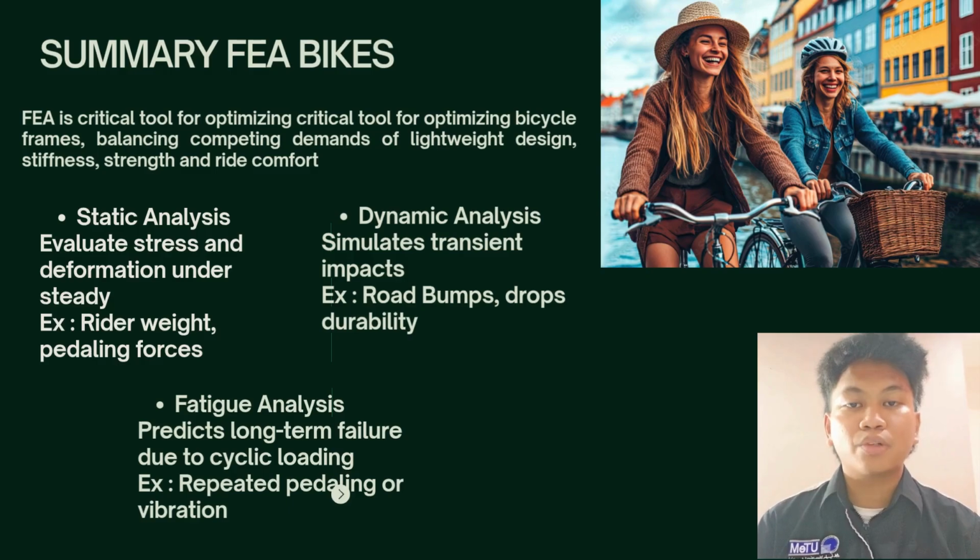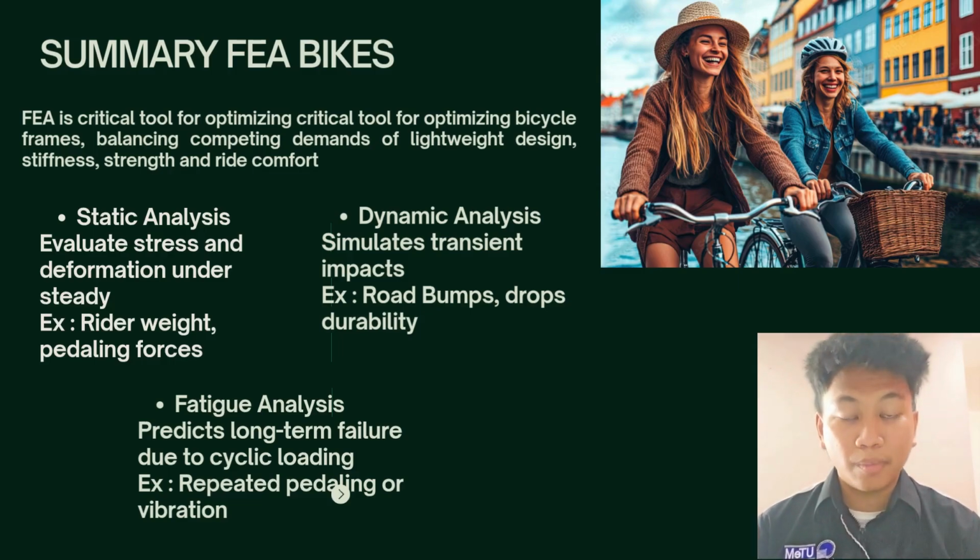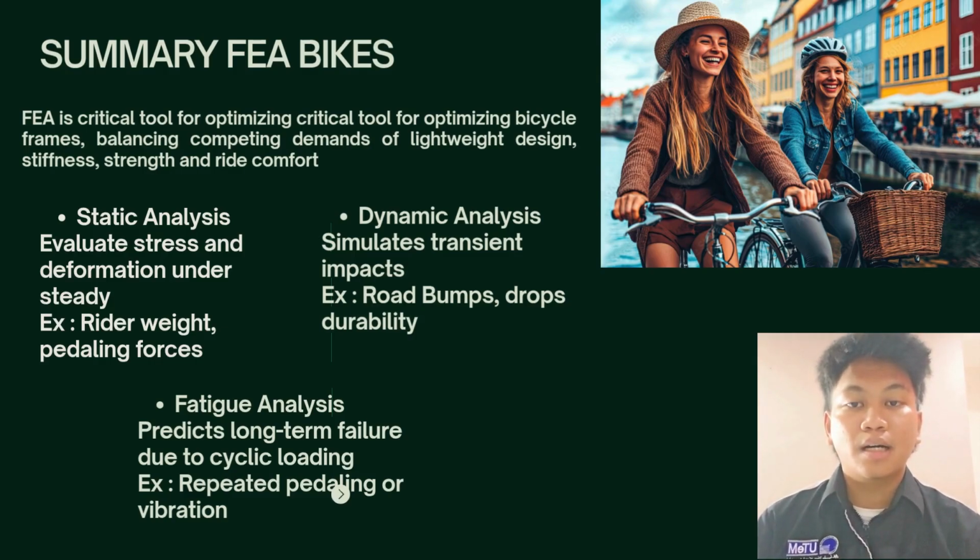Second, composite material behavior and optimization for additive manufacturing. Next, in composite material behavior, many FEA models assume uniform properties, ignoring crucial fiber orientation effects in carbon fiber frames. This limits accurate failure prediction. Research into micromechanical modeling of composites is vital here to better predict failure.